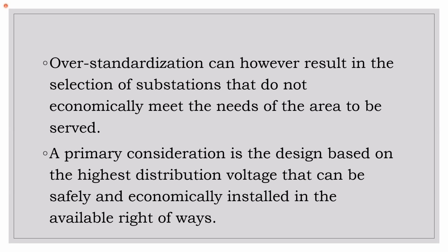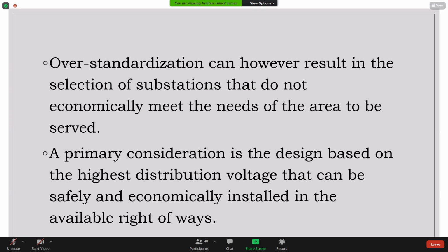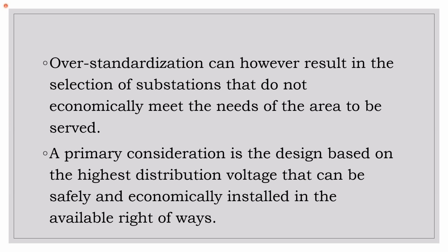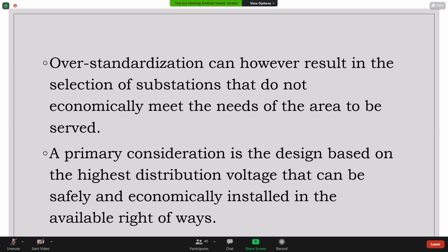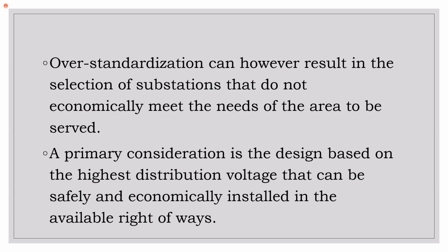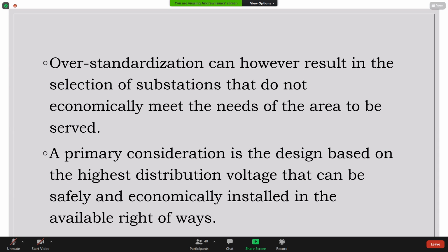So if the standard thing is that you have double breaker, double bus, right? It doesn't mean that when you build a substation to serve that new community that is being built in the hills of Clarendon, that you're going to use double breaker, double bus. You may be able to do a single breaker, single bus down there, and the people will be happy. They don't mind losing power once a year, right? You don't need to. So you have to consider these things.